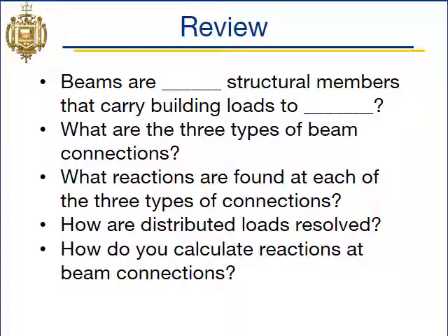How do we resolve distributed loads? We find the area under the curve of the distributed load. That's the magnitude of the equivalent point load, and the location of that point load is at the centroid of that area under the curve shape. So if it's a rectangle, it's right in the middle of the distributed load. If it's a triangle, it's a third from the big end.